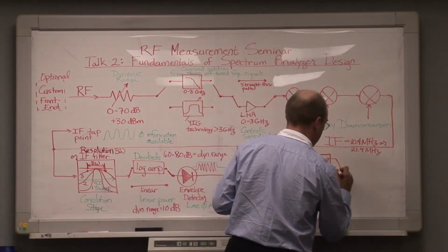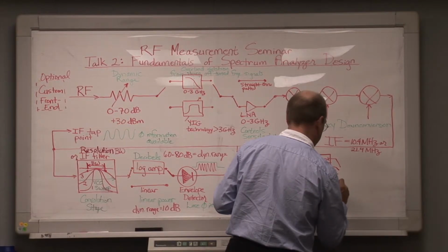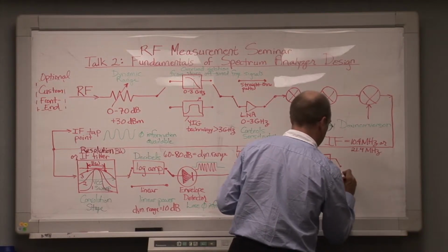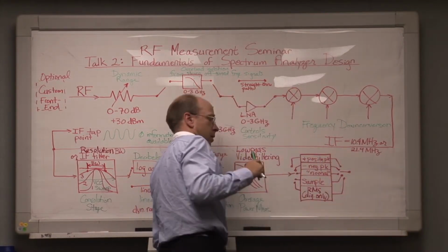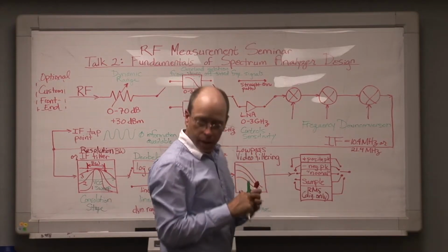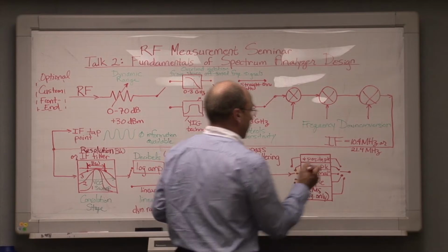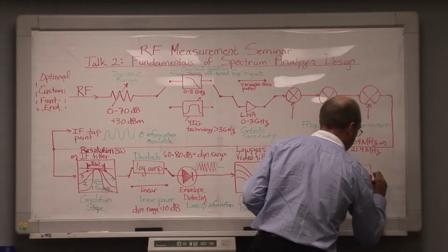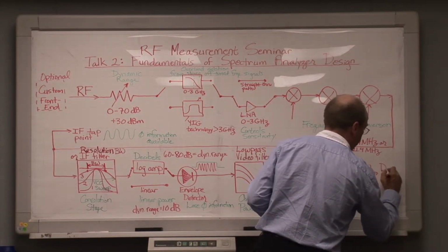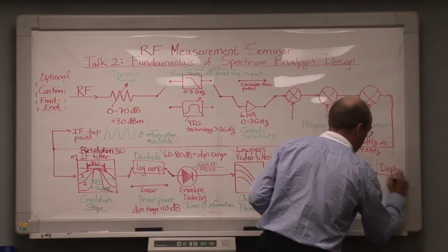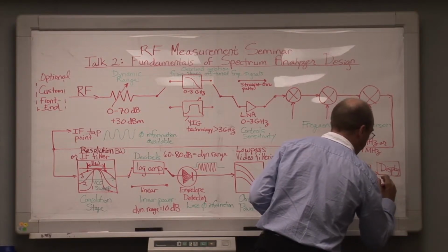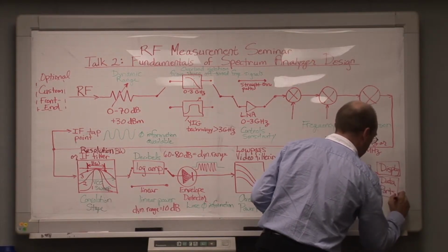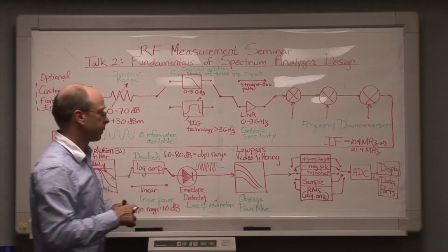And over here we have the same functionality built in reverse for the switch circuit. And lastly, we pass through an analog to digital converter, and then we go out to the spectrum analyzer display. We also go out to whatever data ports are available in the spectrum analyzer design.